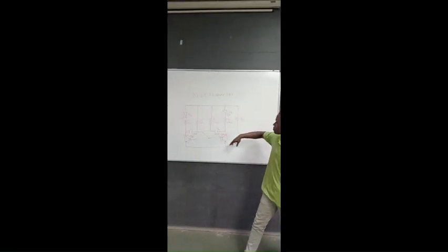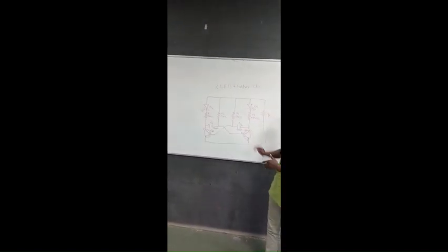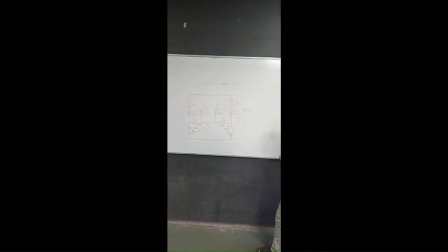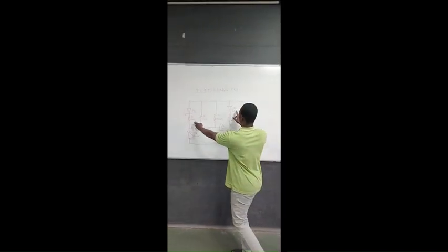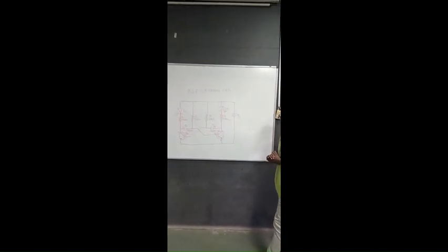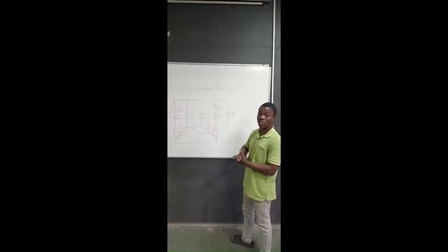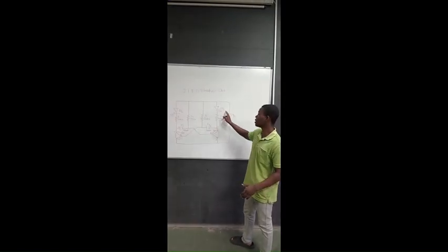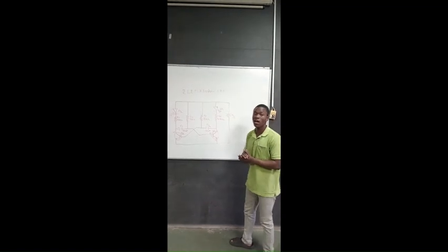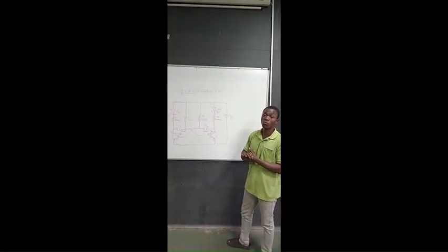Then let me go to the resistors R1 and R4. Both of them are 470 ohm resistors. These resistors, as you see, are connected in series with the light emitting diodes. They ensure that the light emitting diodes receive a safe amount of current.